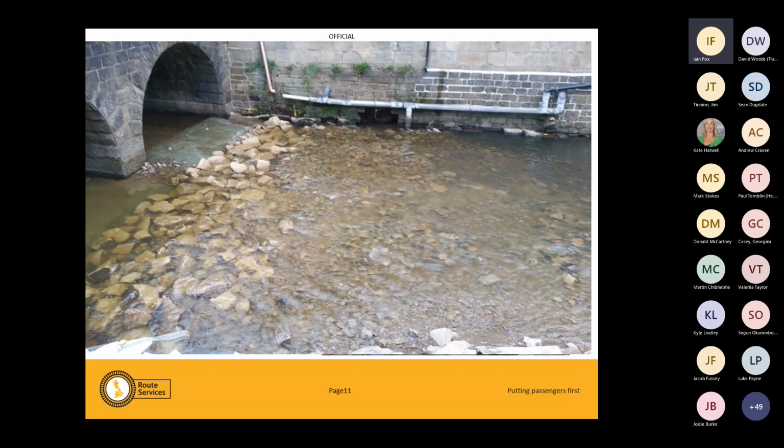Touch on a few other areas of scour then. I know I said there were only a few types, but they all sort of fit into these. But these are things that we don't really take into account. So propeller wash. Think about what scour is. It's fast-moving water that has the ability to move material out of the way.